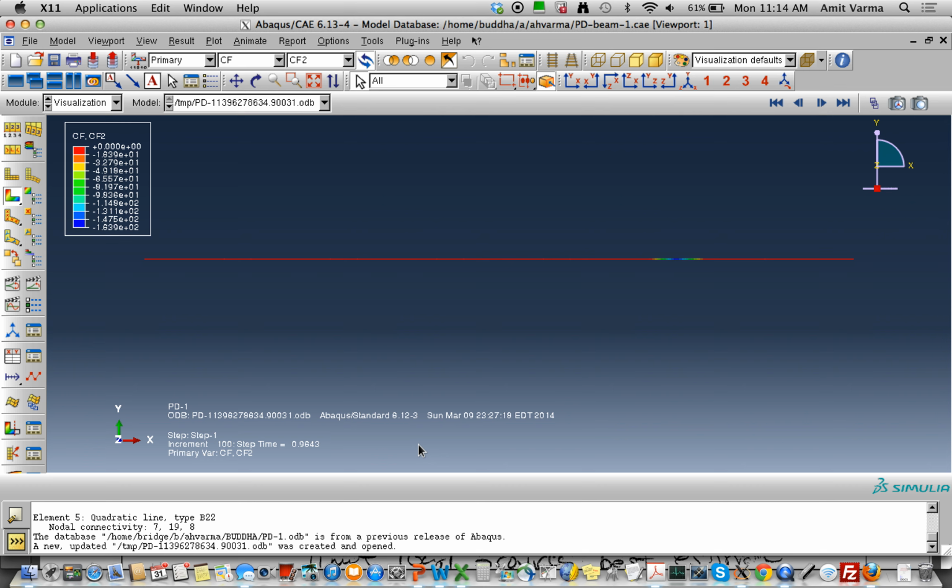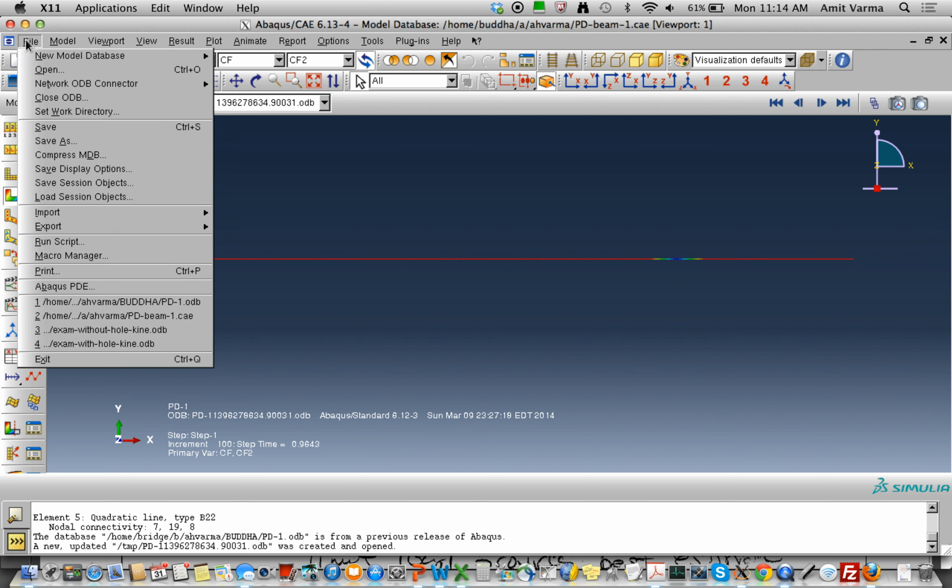The differences will be due to the fact that we are using method 1. It's integrating the entire cross-section response in order to calculate. This is method 2, where you've idealized the moment curvature behavior to be elastic plastic. So there'll be some minor differences associated with the occurrence of plasticity and so on. Okay, so that takes care of